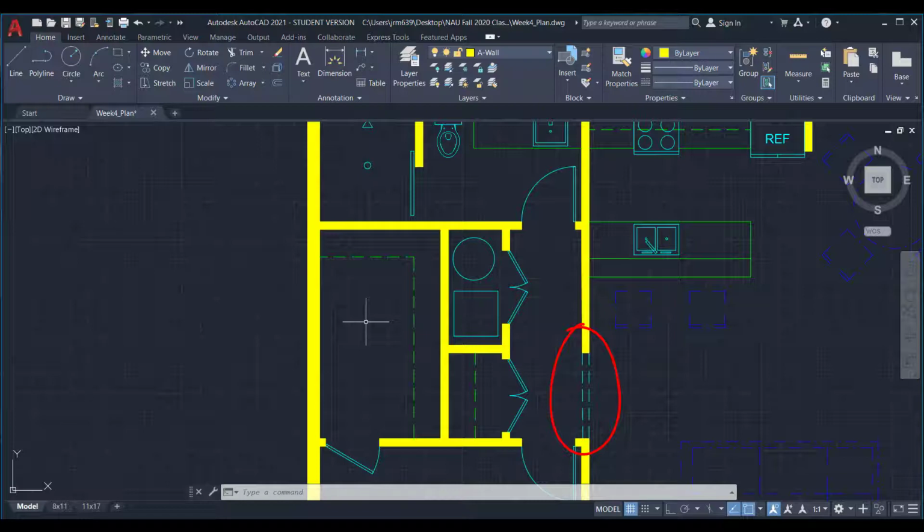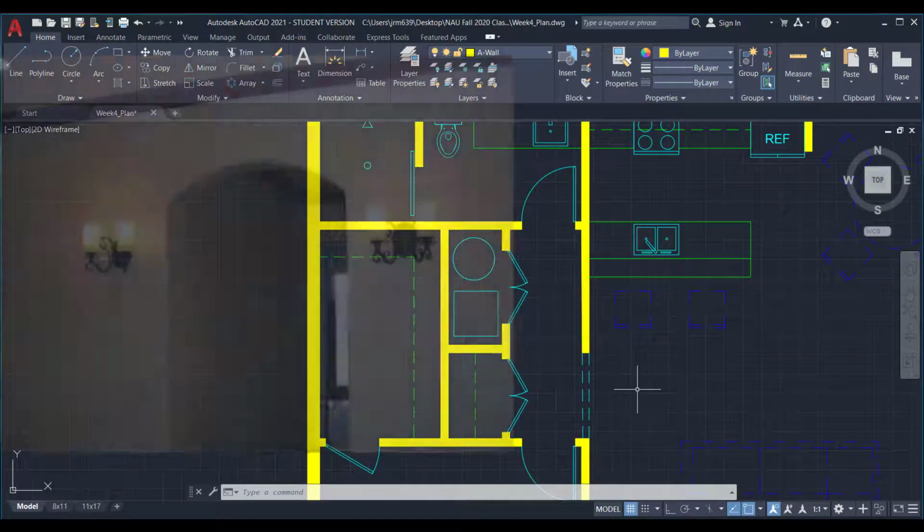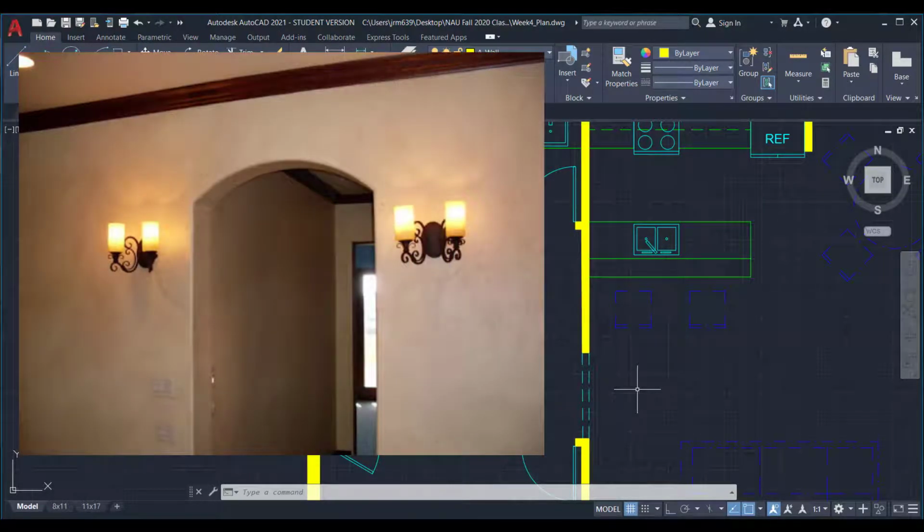That means something different, and it's kind of hard to explain the differences, but it's again just knowing the field and knowing the communication. If you see a dashed line and it looks like it's associated with something like a wall, it means it's hiding. So anytime you see a dashed line in an opening between two walls, that indicates that there is an opening, like a door opening, it's just that there isn't a door. But what's hiding is the fact that the opening is located underneath a wall.